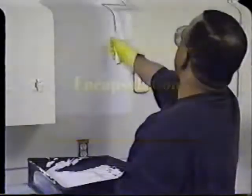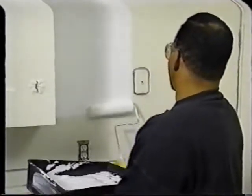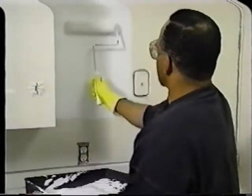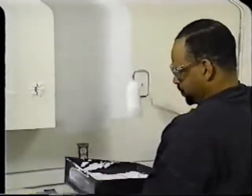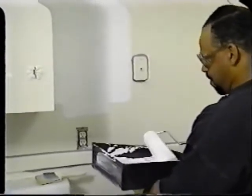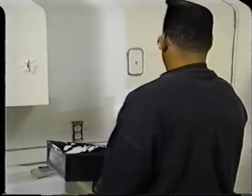Encapsulation is a process that makes lead-based paint inaccessible by providing a barrier between the lead-based paint and the environment. The barrier is formed using a liquid-applied coating with or without reinforcement materials or an adhesively bonded covering material. Unlike enclosures that are mechanically fastened to the underlying structure, encapsulants are primarily attached to the surface through adhesion to